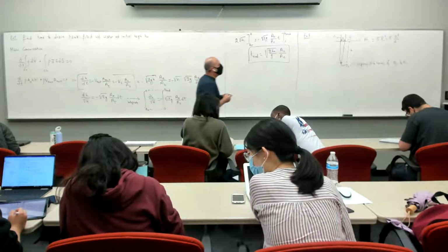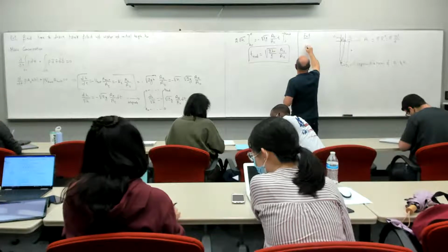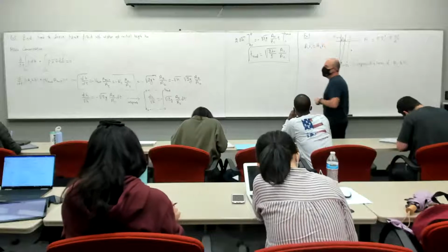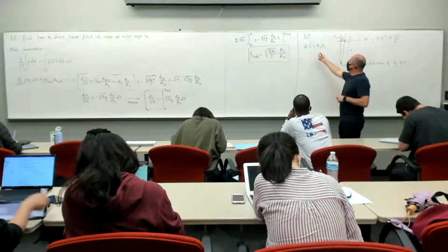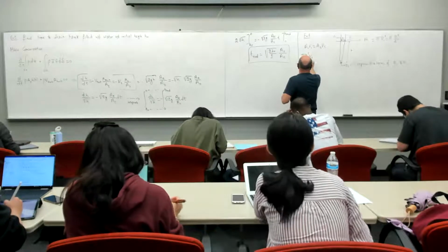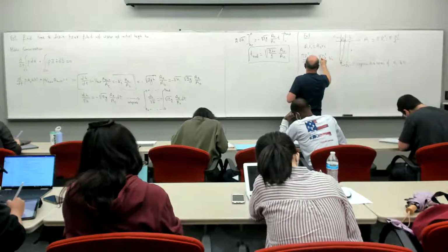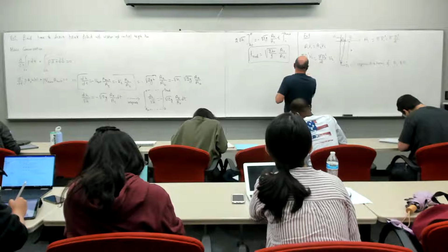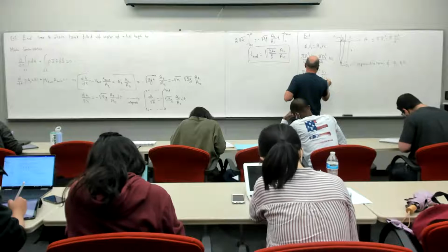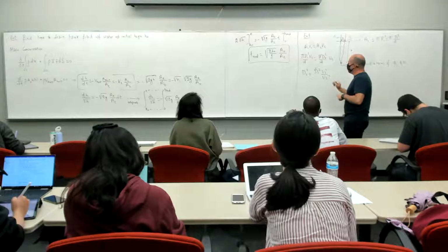Okay, so let me give you mass conservation. Don't overdo mass conservation. Mass conservation is simply A1 V1 equal A2 V2. Okay? You're looking for D2, so pi D1 squared V1 over 4 equals pi D2 squared over 4 V2. So you get D2 squared equals D1 squared V1 over V2. You know V1, you know D1. What is V2?